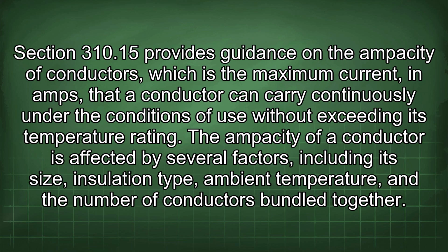Section 310.15 provides guidance on the ampacity of conductors, which is the maximum current in amps that a conductor can carry continuously under the conditions of use without exceeding its temperature rating. The ampacity of a conductor is affected by several factors, including its size, insulation type, ambient temperature, and the number